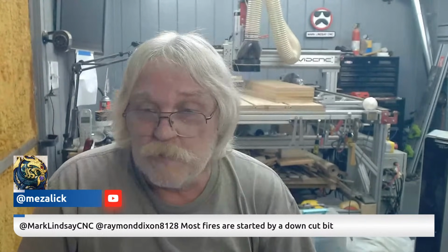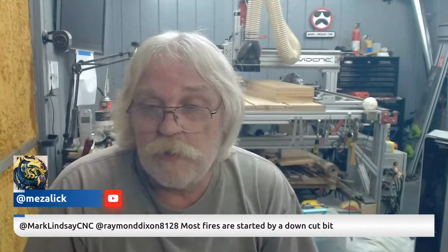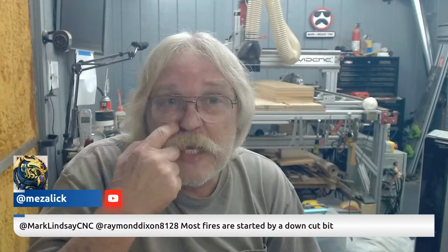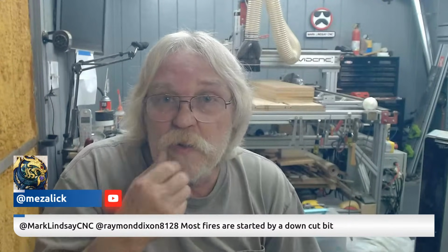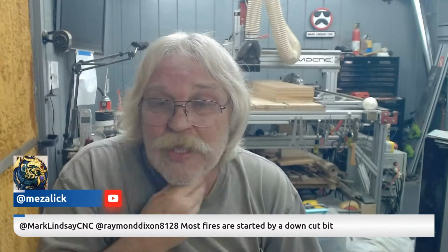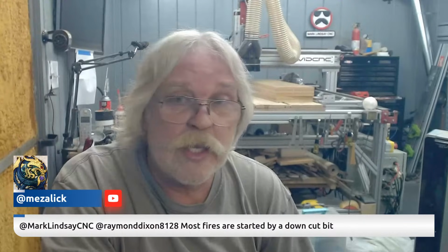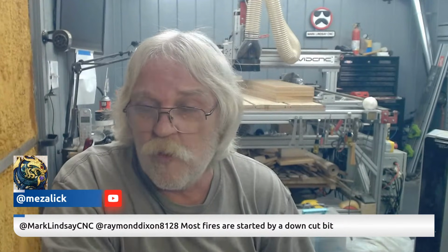Michael also says most fires are started by a downcut bit. I would tend to agree with that, Michael. I learned my lesson early on. It was like the second project I had ever done, and I was drilling a lot of holes. Dummy me, not knowing any better, I used a downcut bit to drill holes. And by the time it got into the 3rd or 4th hole, I had started a fire.